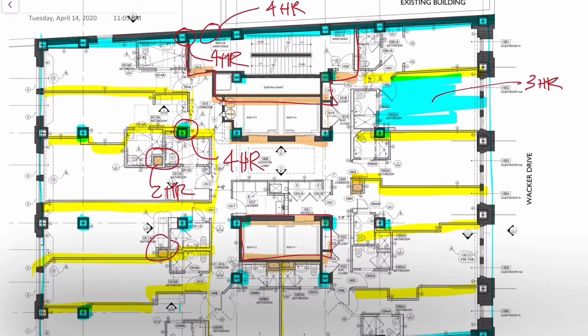And in the case of this particular project, these walls are actually 2-hour rated, mainly because of the sound resistance of the walls. So while in this project they're 2-hour, they're really 1-hour fire rated requirements. And so that's for all these guys that are separating the sleeping rooms. So I think that really covers everything in this particular example. And maybe what I'll do is next I'll show you guys what some of these walls actually look like.